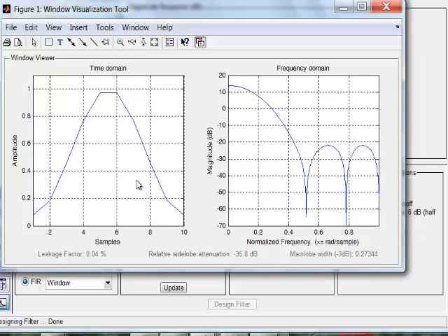We don't take a window and then just jump to the next one. Normally every window has some overlap with the other, at least 50%. So only some of the samples are really important for this window, and the rest will also be considered in the next processing window. That's why the Hamming window makes it smoother in the time domain.